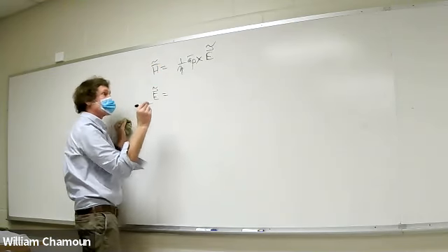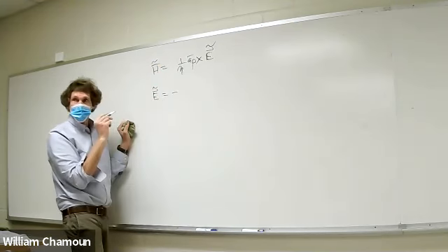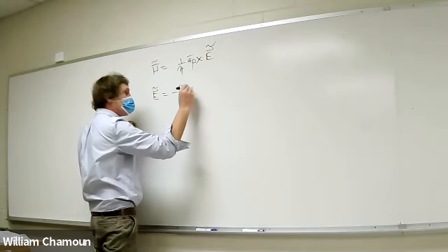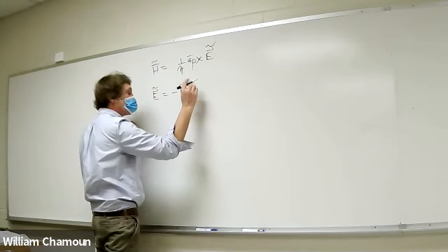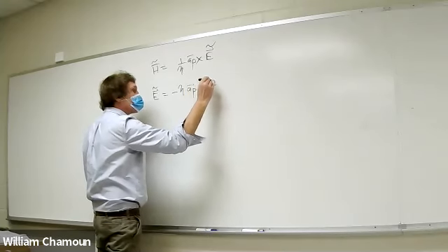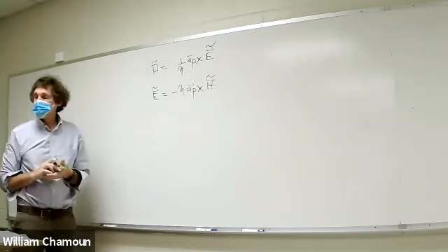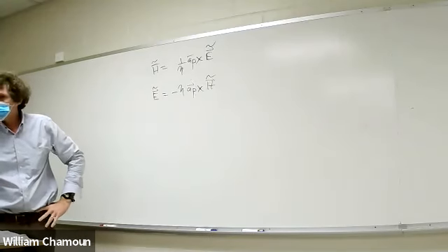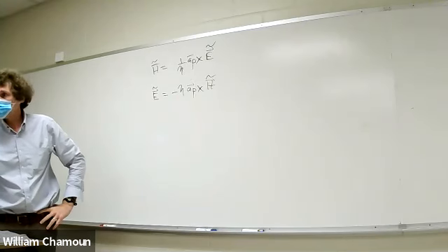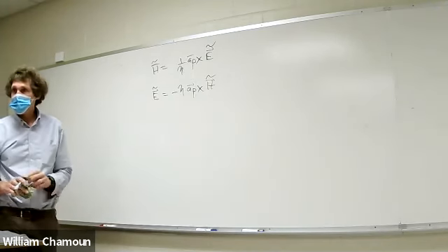All right. How do you get the E field if you know the H field? Something like that, but there's a minus sign, isn't there? Minus, and then there's an eta in the region, right? Unit vector in the direction of propagation, crossed into H. These are in your book. I don't remember the page, but these are the two golden things you use for plane wave propagation. If you have one, you get the other, related to the incident, reflected, or transmitted field. Y'all with me? I don't know where it is in the book. Somebody can find it if you want a page.